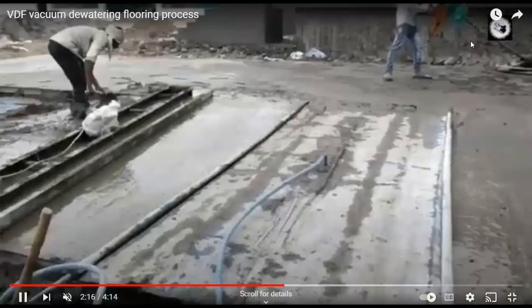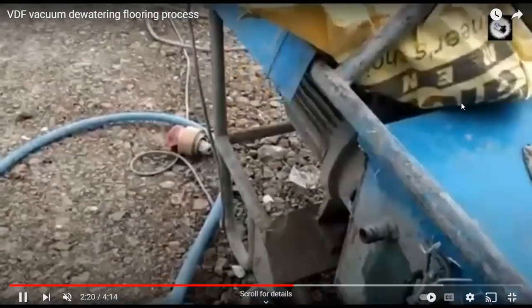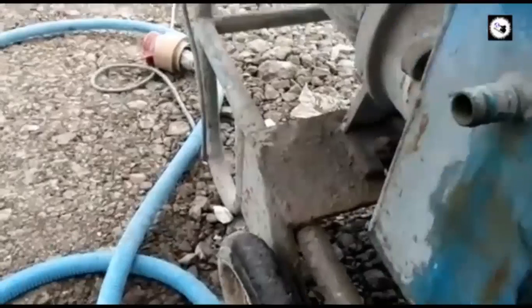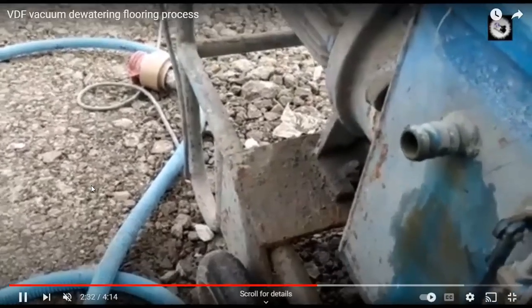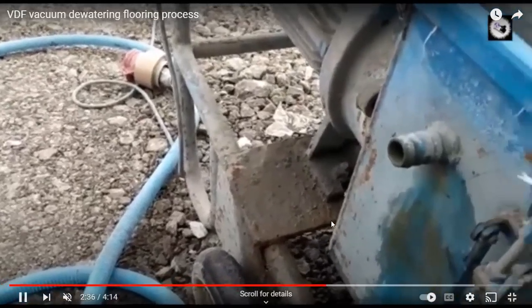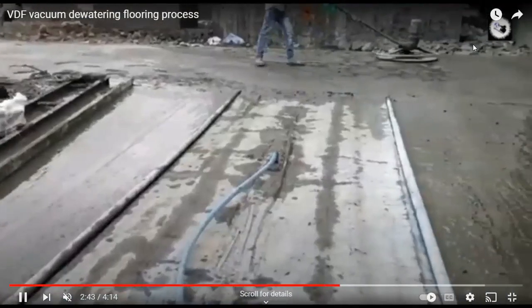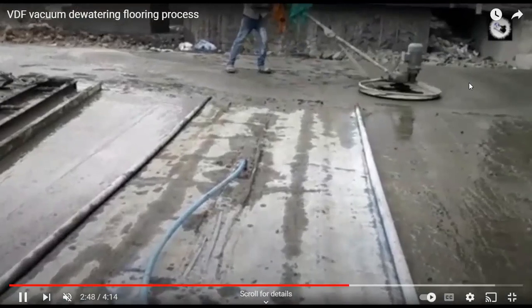So you can see the personnel here. The worker is able to stand and work over the concrete floor without making any footprint. He doesn't leave any footprint, which shows that the concrete floor is ready for finishing. We have removed enough water to achieve strength from the concrete. By standing on it, the personnel is able to do the troweling process, and he finishes the surface very smoothly.